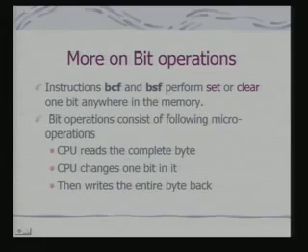So the instructions we have seen, therefore, the BCF and BSF perform set or clear one bit anywhere in memory. And bit operations consist of the following micro operations. CPU reads the complete byte, CPU changes one bit in it and then writes the entire byte back.